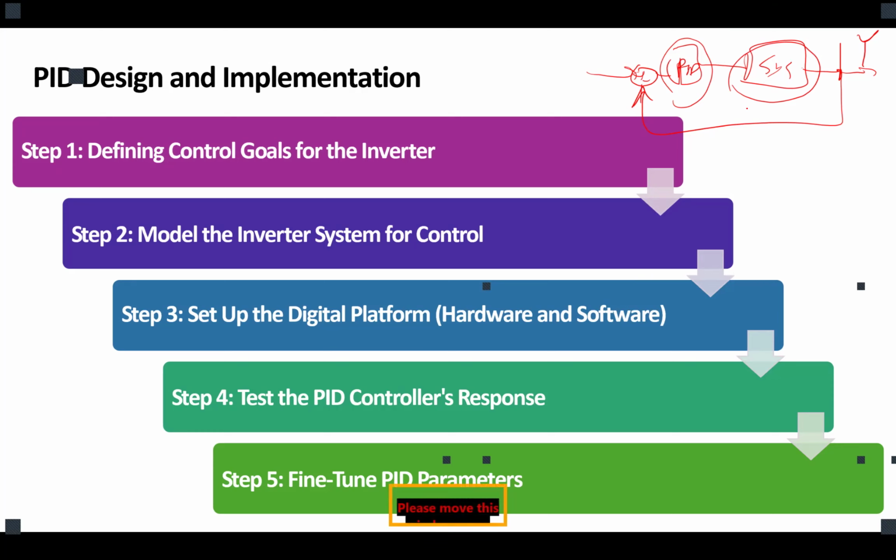You can also use just simulation, it's going to be the same. But if you want to theoretically design your PID, the best tool is the S domain. So you run a KVL or KCL over your inverter. Input is the correction signal. Output is the output of the inverter.